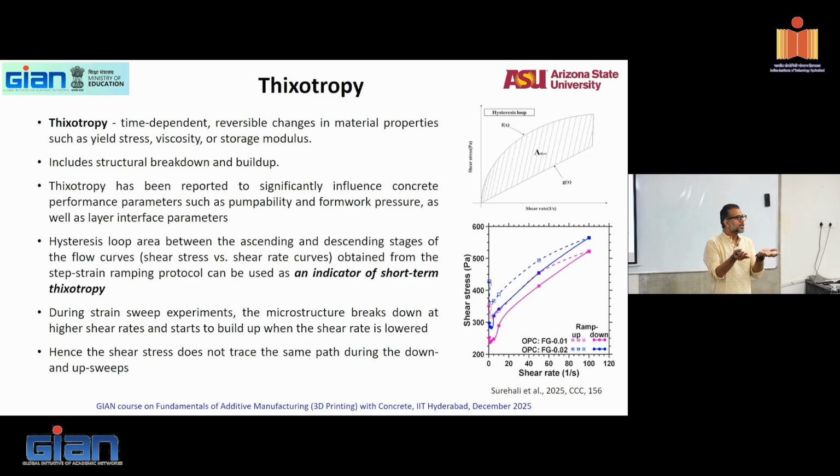Building up. So if it is not building up at all, I'll come back along the same line along the shear stress versus shear rate. But if I'm building up, you will see that difference. You will see a structure building up. The area under it is generally a simplistic measure of thixotropy. There are better ways to measure thixotropy as well, but this is one way of measuring it.